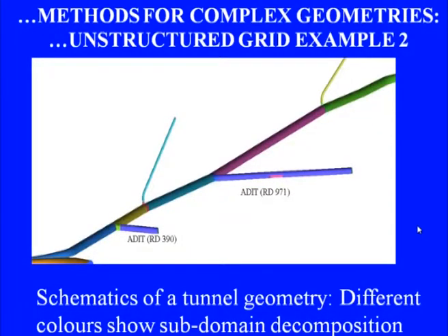This corresponds to a highway tunnel. It is a long highway tunnel and it has got many adits, and these are what we call shafts for the outlet air. The air is sucked from there and discharged to the outer atmosphere, and the adits are additional ducts through which we can access the tunnel during emergency situations. They are also used to supply fresh air inside the tunnel.